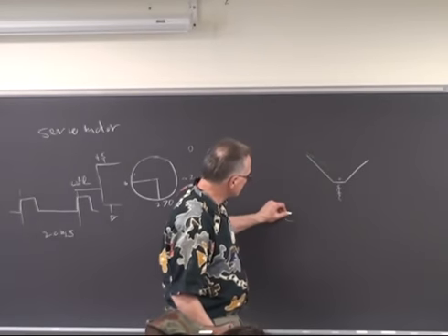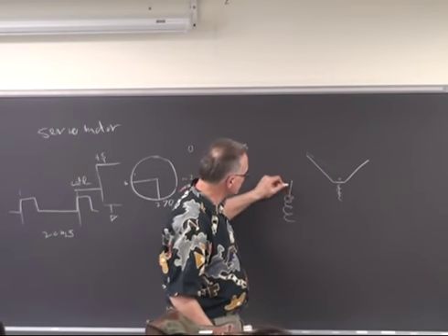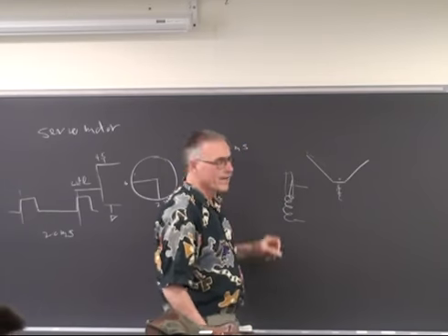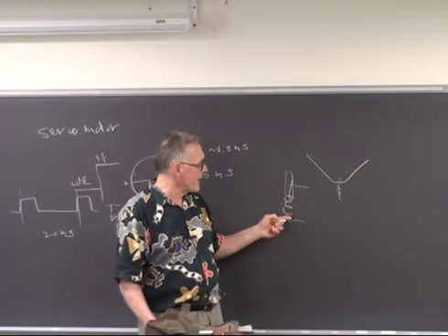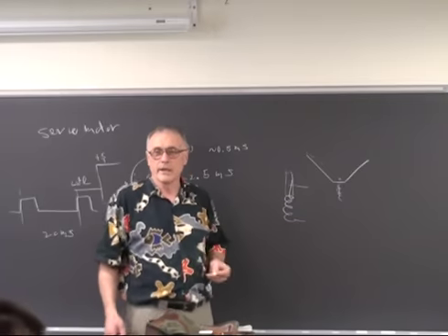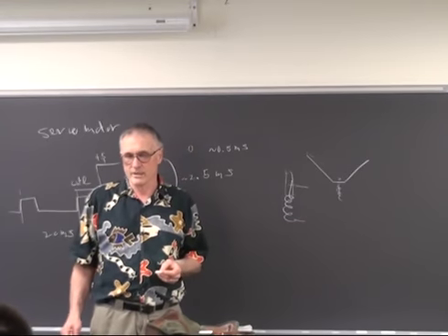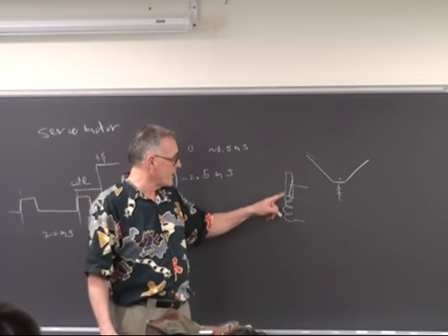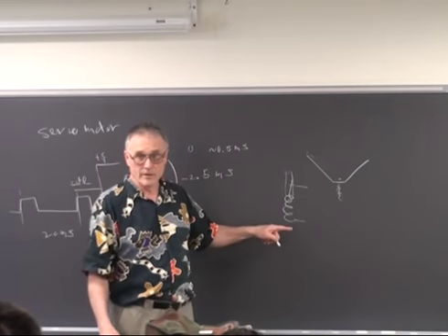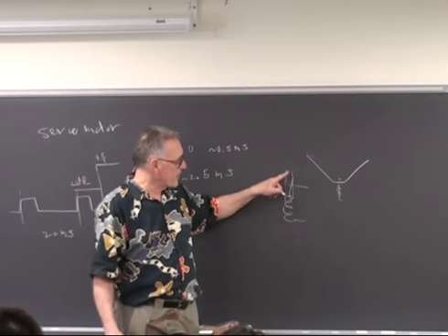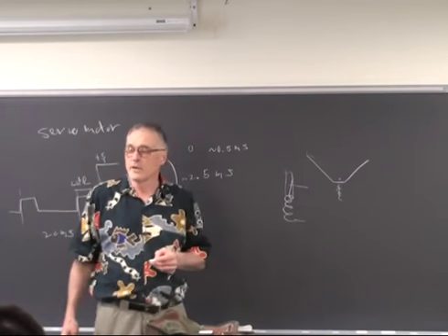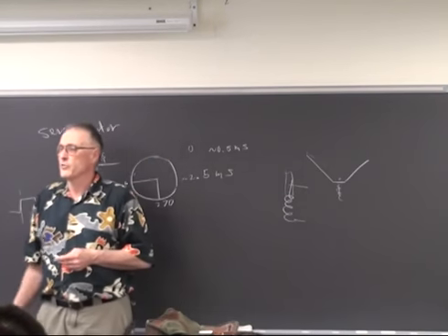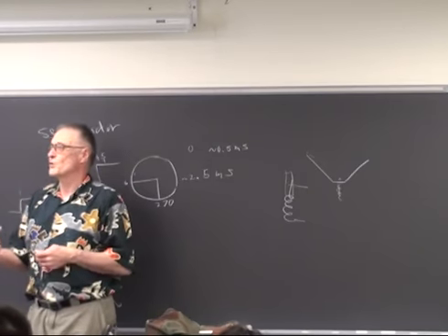It's a coil. It's an electromagnet with a piece of iron hanging in it. You turn on the magnet, it pulls the iron in. It is all or nothing. This is not a proportional device. It is digital. The armature is either out of the coil or in the coil. Nothing in between. It would be good for digital-like motions.